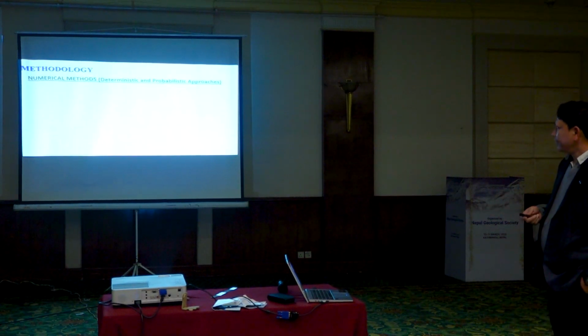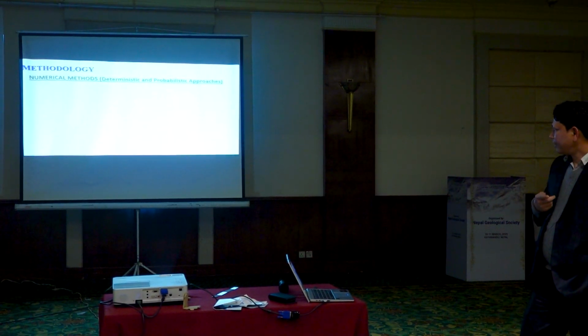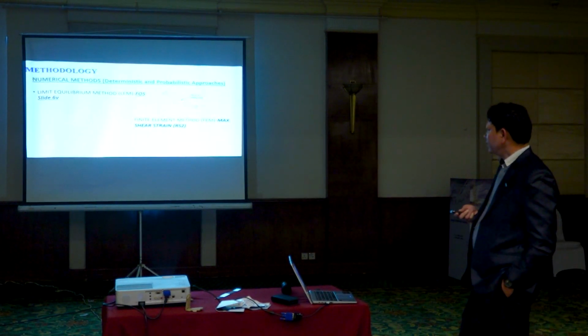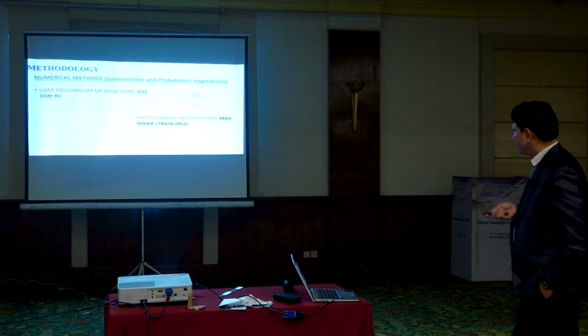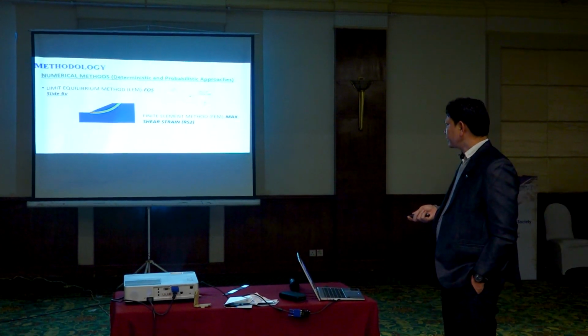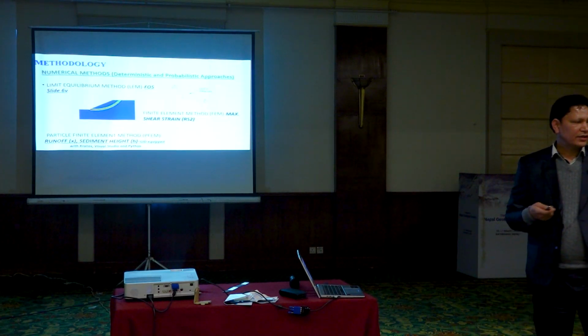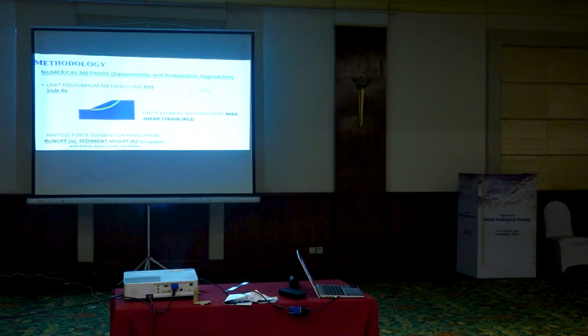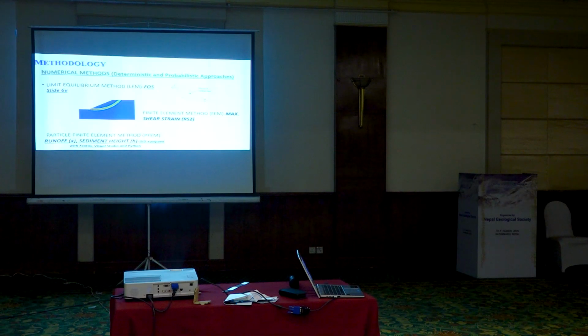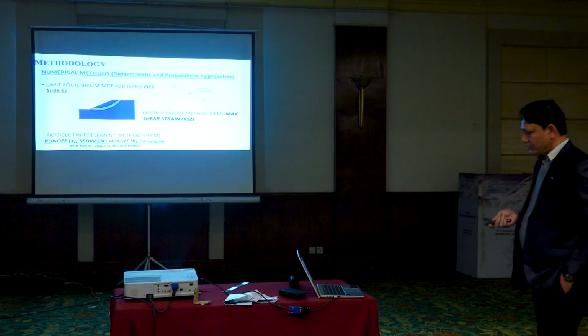And in methodology we have used three methods, as I have already told. I have used the limit equilibrium method, which determines the factor of safety. Another one is the finite element method, which determines the maximum shear strain area and also determines the stress reduction factor. And the next one is the particle finite element method, the PFEM, as already mentioned by Mr. Vidas. It gives us the runout distance and the sediment height.